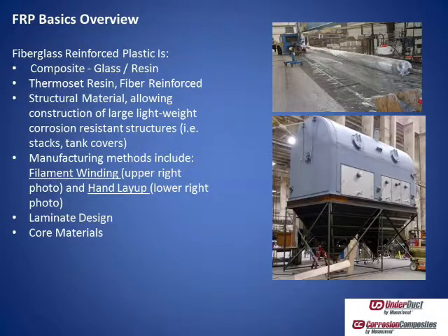And the thermoset versus thermoplastic is a key thing. The thermoplastics are those that can be heated up and reused or melted, essentially. Thermoset plastics, the epoxy, the polyester, the vinyl esters, once they're cured with heat, you can't melt them. And that's why they're such a strong item to use in our industry.